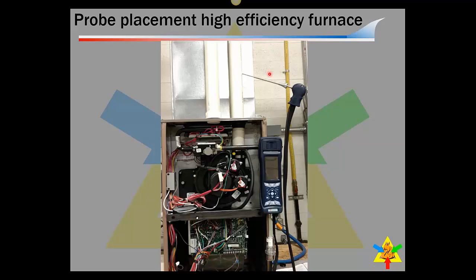You can also go to the termination of the flue. That's a great place to do it also, is at the termination. Okay? And on these flues, we need to make certain that we plug the hole, because high-efficient furnace flues, or furnaces with PVC flues, this flue is under positive pressure. This inducer motor is now actually pressurizing this pipe and forcing the flue gases out. If we leave an open hole in it, flue gases and water vapor are going into the home.